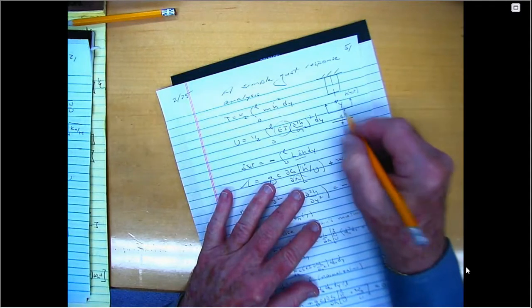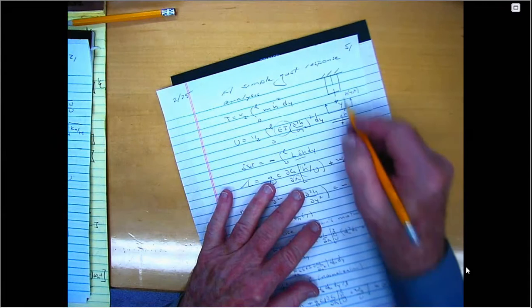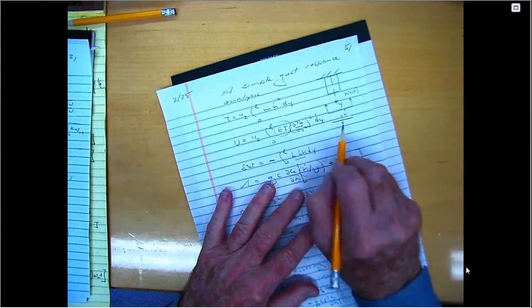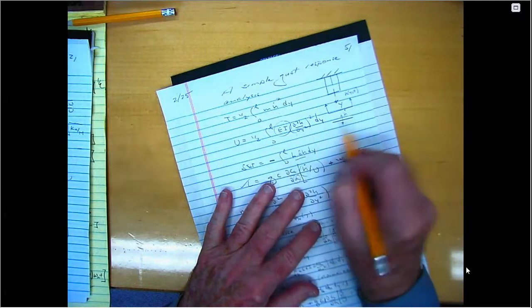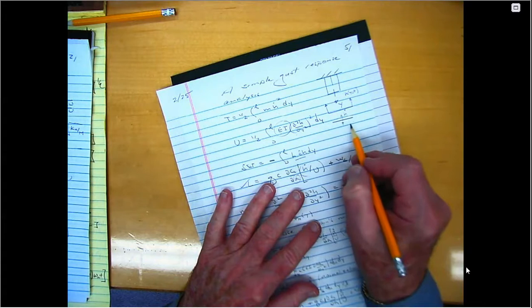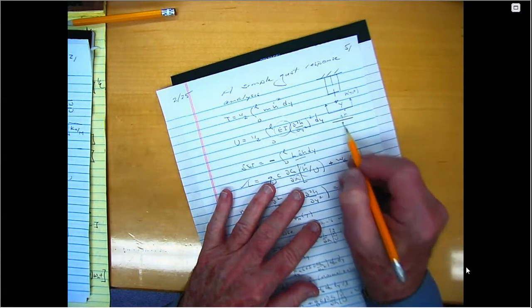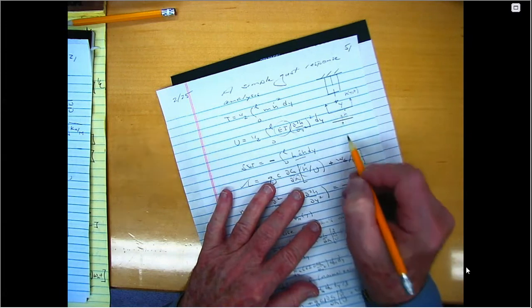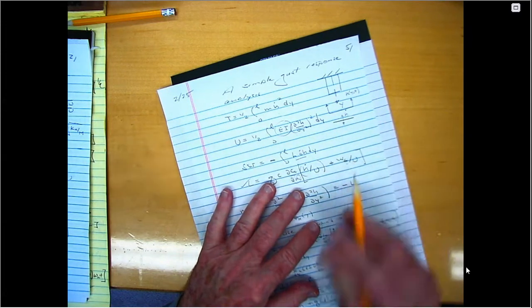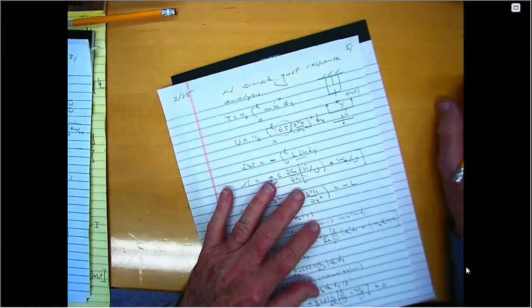But it's also flying through a gust field where the gust has a component in this direction, w_G. And the gust also has a component in this direction, but that's so small compared to U that we neglect it. Whereas this isn't small compared to what was otherwise there, because before the gust, there was no component in this direction. It's this component of the gust that gives rise to an effective angle of attack and causes lift to be produced on this wing.